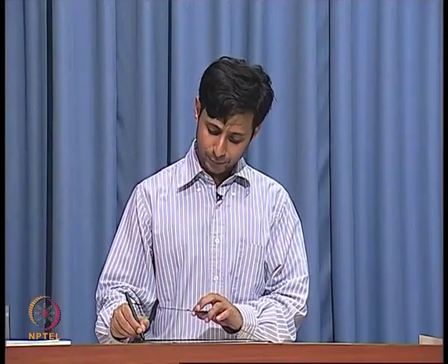So, as you progress over space, you are going to get attenuation. You start off with a sinusoid on the load side. As you progress over the transmission line, you get attenuation, because there is resistance. As far as voltage is concerned, there is resistance. If you think about current, then there is conductance, which provides a leakage path, and as a result the magnitude of the current is going to decrease.